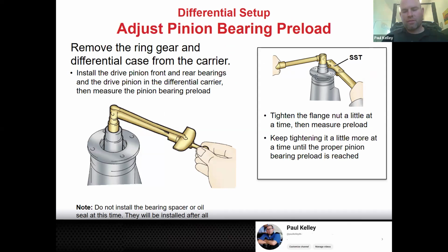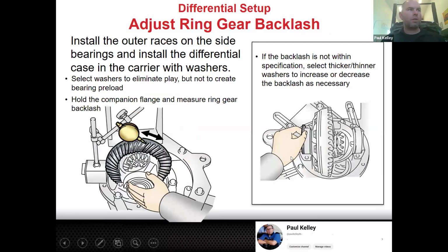That's the thing. It's a formula. It's pinion plus side gear is total. So if you don't at least know pinion, you can't determine what side gear is, even if you can measure total. If all you know is total, it's A plus B equals 10. How much is A? How much is B? I don't know. But if A is 8 plus B is, let's say, 10, then you know B is 2. Right? So that's how you determine the side gear preload. You have to know the pinion first, and then you can measure the total, and by the calculation, you can know what the side is, okay?